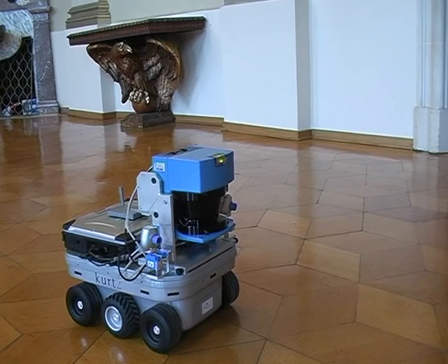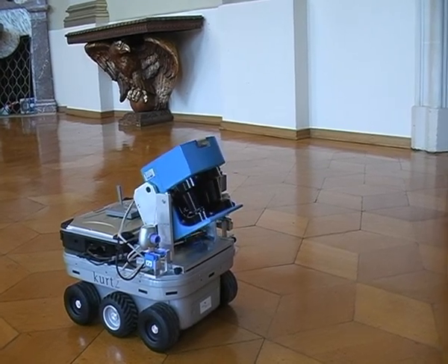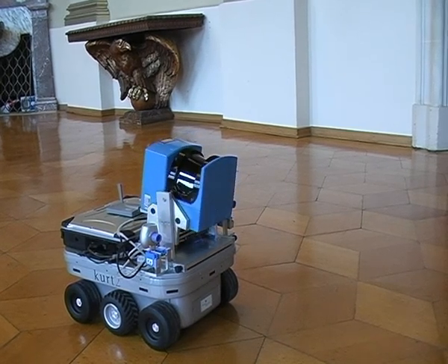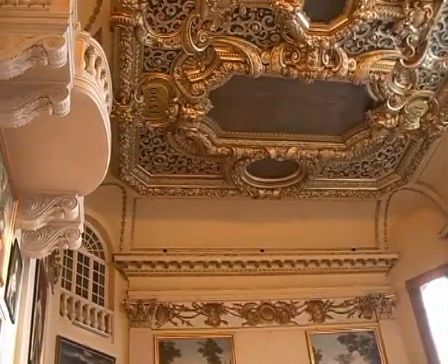A fundamental problem in the design of autonomous mobile cognitive systems is the perception of the environment. Kurt is equipped with a fast and reliable 3D laser scanner. The 3D scanner is built on the basis of a custom 2D rangefinder. The laser scans the environment horizontally and vertically with a precision of 1 centimeter. It detects all objects, even the cameraman taking the scene. From the scanned 3D data, a virtual environment is built. Thus, Kurt can plan trajectories and locate objects, for instance a chair at a corner or door.